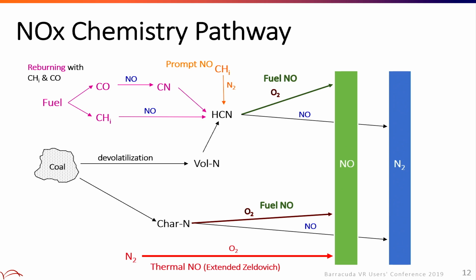route again. And there's another chemical route for control methodology. Sometimes you use a reagent. A nitrogen-containing compound can react with the NO to form N2. But of course, if you put that chemical reagent in the wrong location, it can be oxidized, and you are forming NO instead of converting that to N2. So that's very important. Another thing is char can also reduce NO.